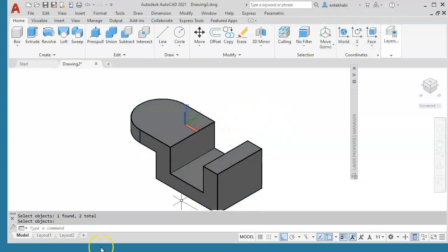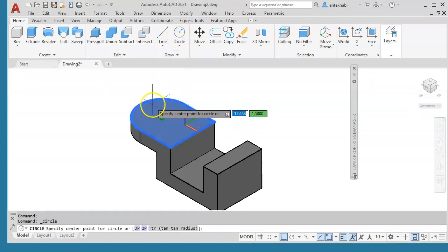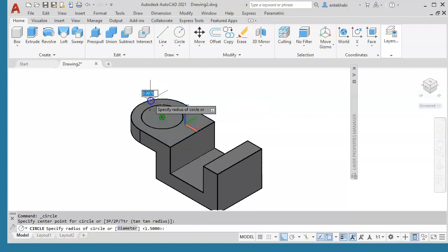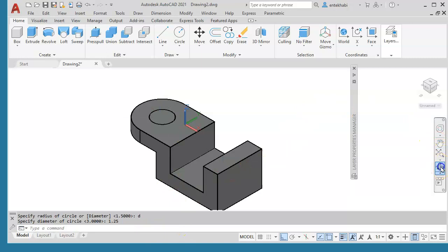Okay, I'm going to draw 2 more circles and extrude cut. In other words, we need to subtract those circles. So that's the same concentric with the arc. The diameter for this one is given as 1.25. Since I'm in the radius option, you can switch to diameter and type exactly 1.25. And let's extrude this one.